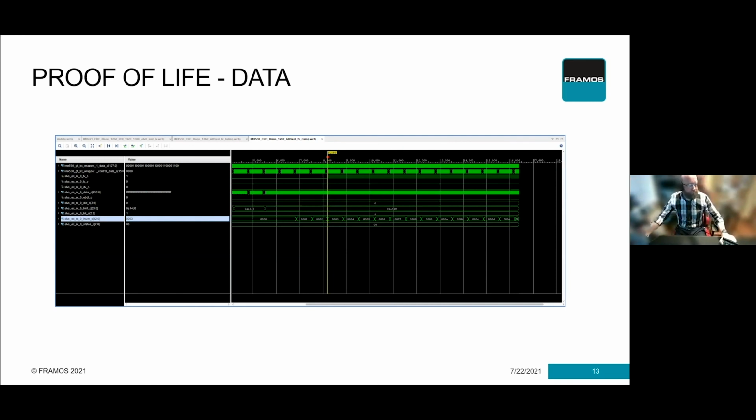Okay. Another question here is, how do you determine if an error is at the sensor or in the FPGA? How do you isolate the location when you cannot prove it on the hardware? So it comes down to you have to build your evidence. Test patterns are fantastic for that. So let's say the image your system is losing sync with the image sensor.